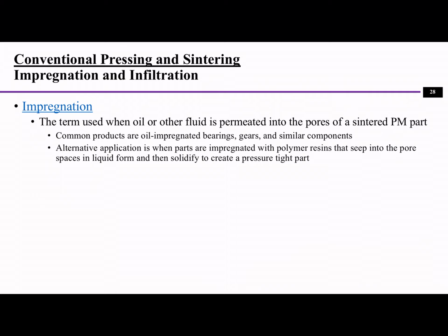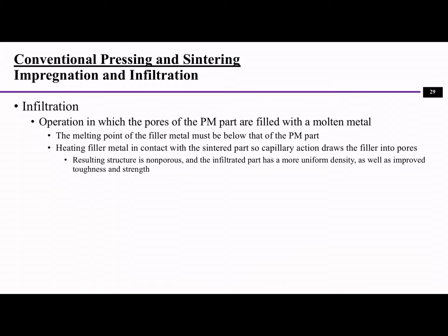That makes them self-lubricating. Infiltration means we are filling those pores with molten metal. Usually the metal that fills the pores is called a filler metal.